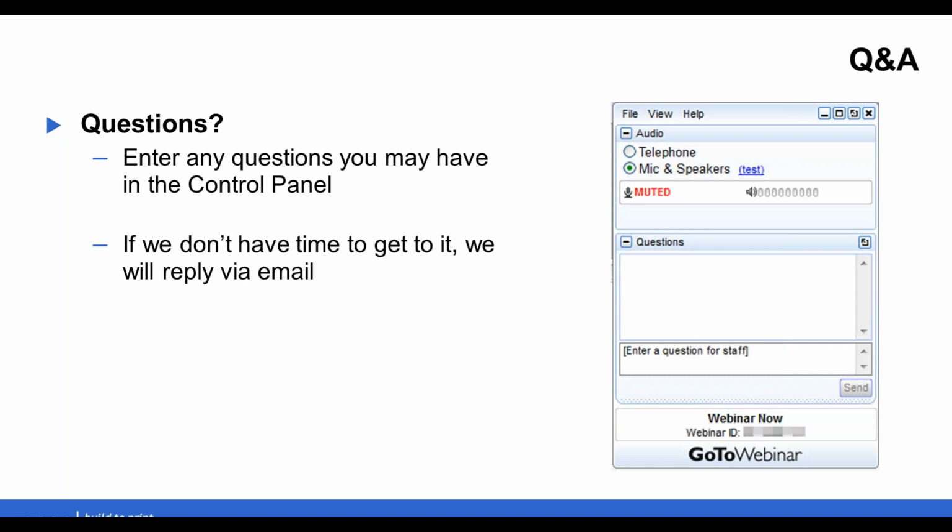There's a bunch of ways to answer that question, but a prime and paint operation probably has the best resilience to the elements. It's also probably one of the more expensive, but if you need that structure to serve as a path to ground, you'll need to mask an area and add some kind of grounding tab. That masked region that you're adding the grounding tab to should have a chem film processed in that area.